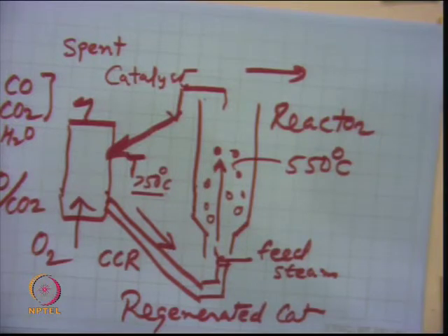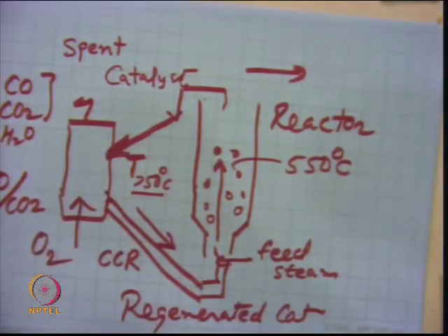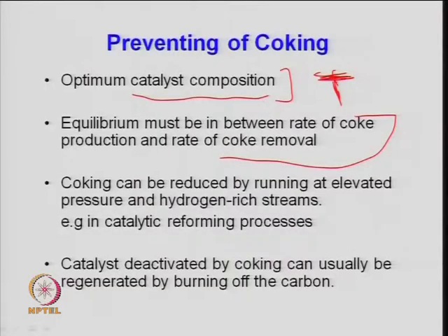This is what you need to look at when carbon deposits on the catalyst or the catalyst deactivates. So, a reactor-regenerator combination or a novel kind of reactor system design is required. You need to look at how much carbon is depositing on the catalyst per gram of catalyst per unit time, and how much carbon is being removed from the catalyst.